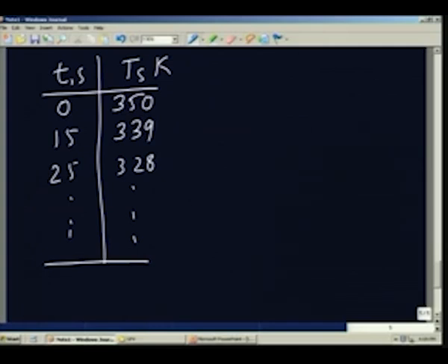So, how do we get the emissivity from such a cooling curve? That is what I am looking at now. What I can do is assume the cooling curve, solve the equation which I gave a little while ago for different values of epsilon, and find out that particular epsilon which gives the best match with the data you got.